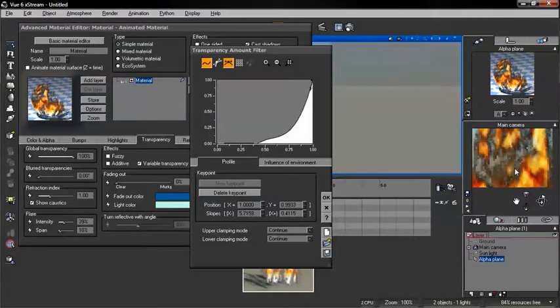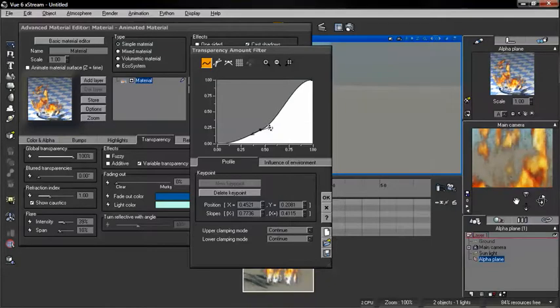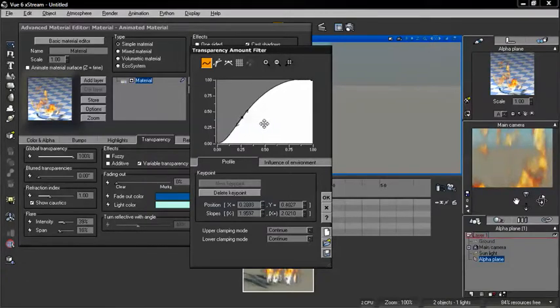And drop it down even further, and now we really see all of those artifacts showing up, but much more intense flames. But typically you'll want to adjust the intensity of your flames not by the transparency map, but by your luminosity and your luminous value. So we could move that up and take a look, and now we can see we're removing a lot of the artifacts but losing some of our overall contrast.